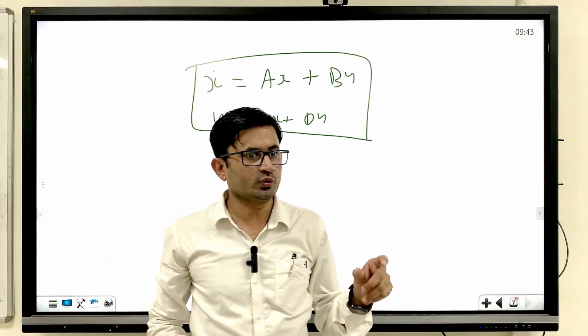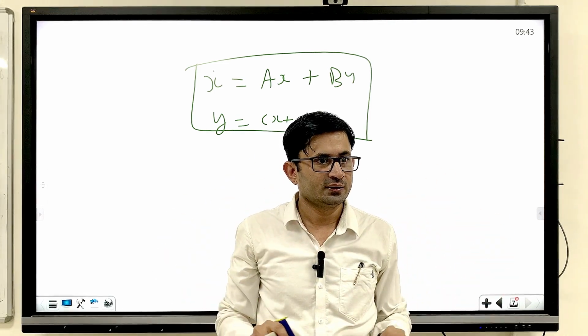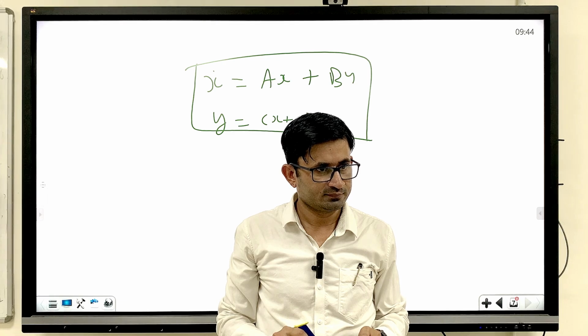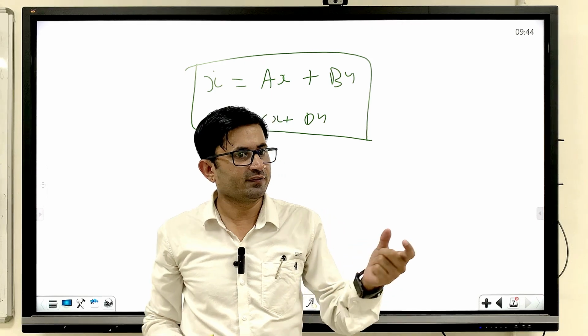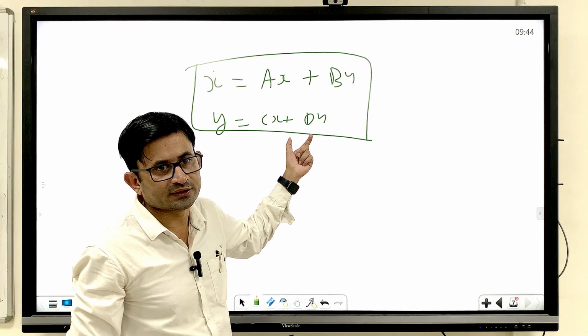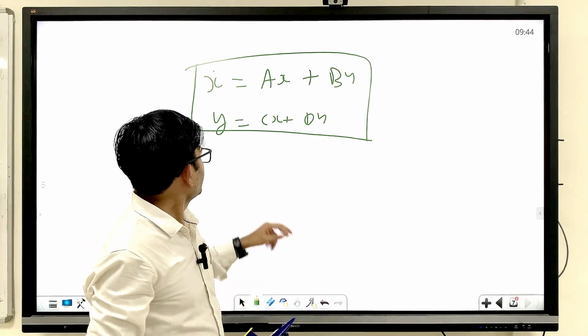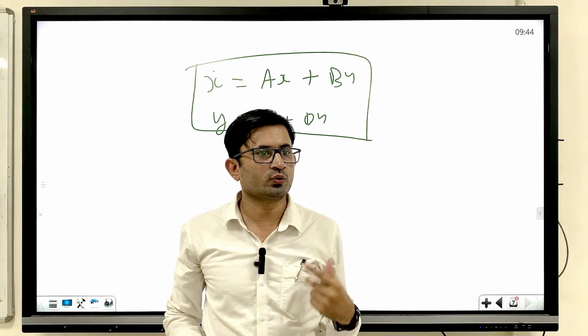So x dot equal to Ax plus Bu is representing the dynamics of any system. You will see, I will take the spring mass system and rearrange it in this form, then you will easily understand. And y equal to Cx plus Du, y is the output you want to control.